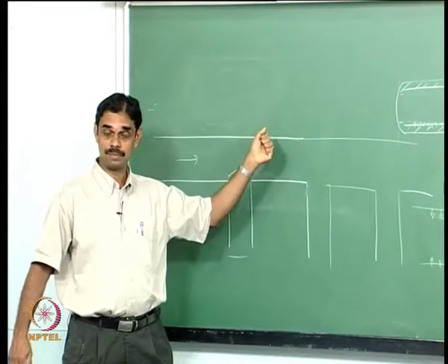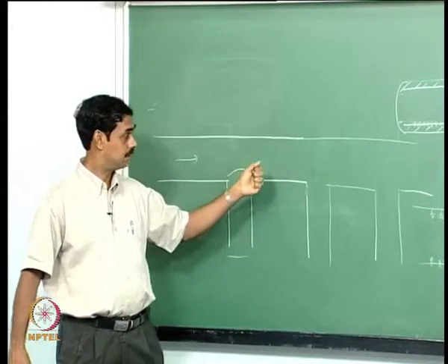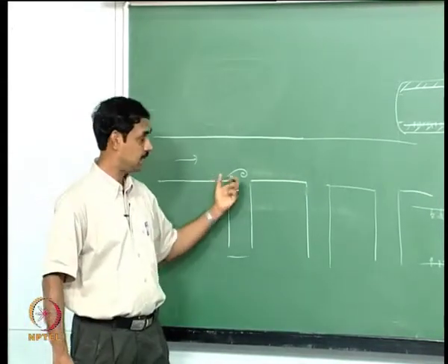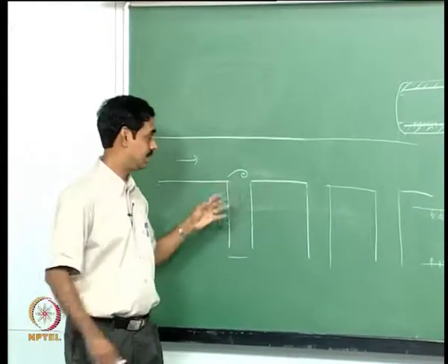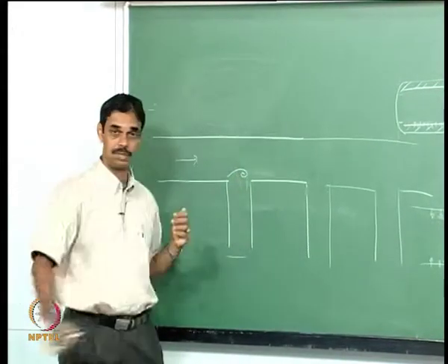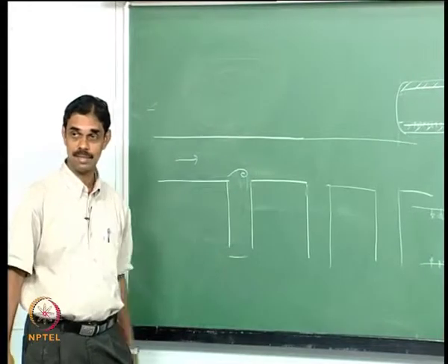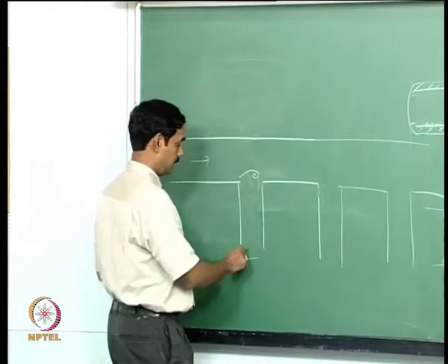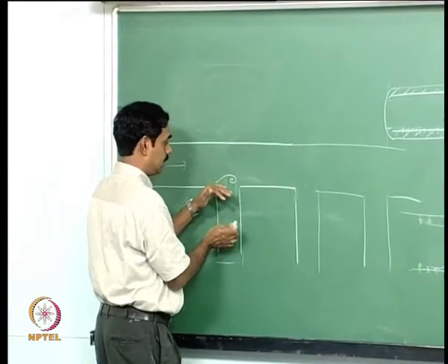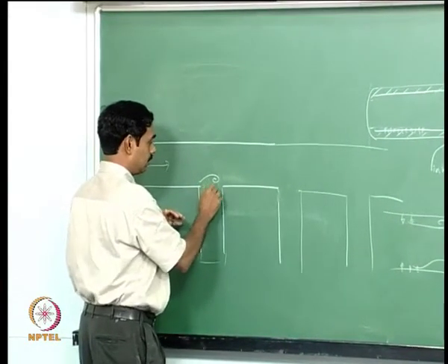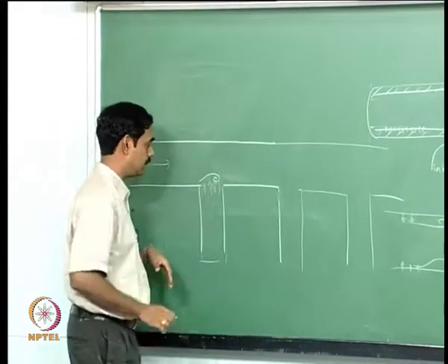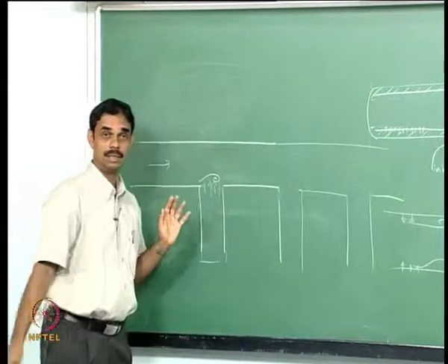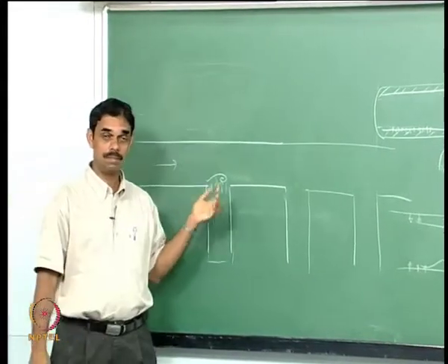So when you have natural gas being distributed this way, anytime you close this branch, if there is a flow, then I think this will not be a problem, because the vortex will be disrupted, but if not, you will have a resonator here and the vortex is crossing the lines of acoustic streamlines, and you have large amplitude oscillations, and then you can cause a lot of damage to the pipes.